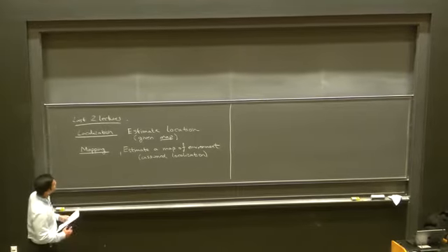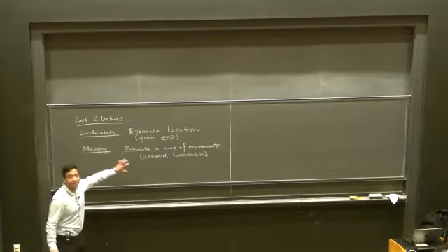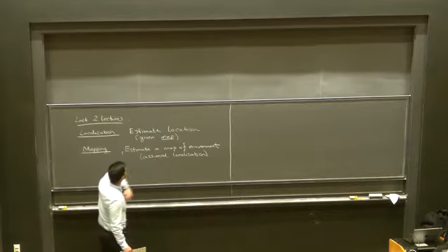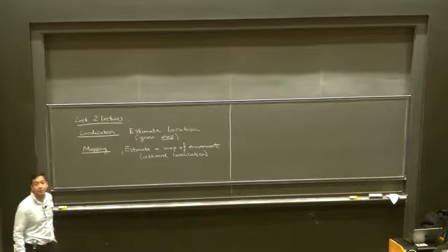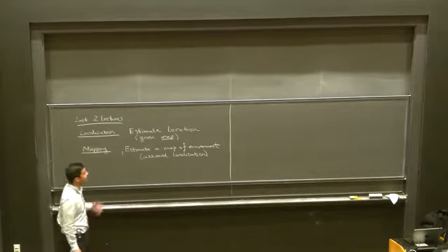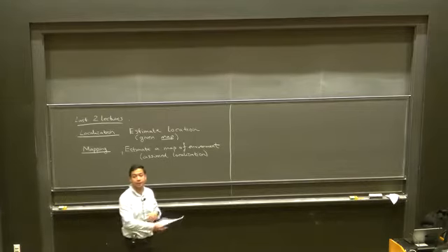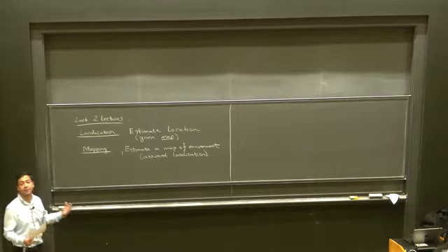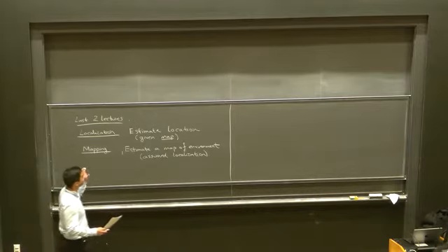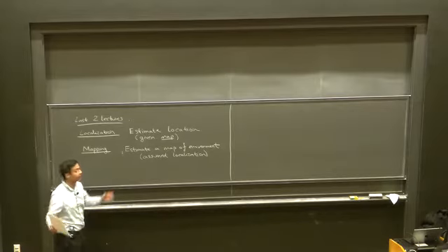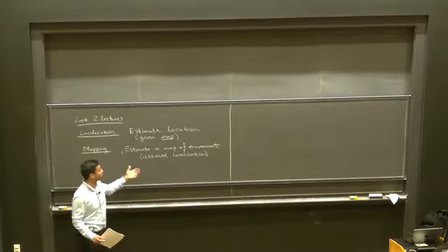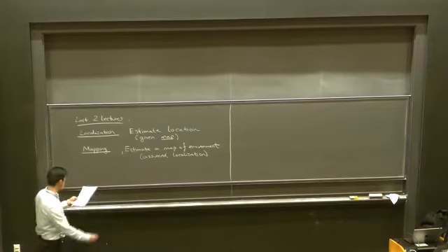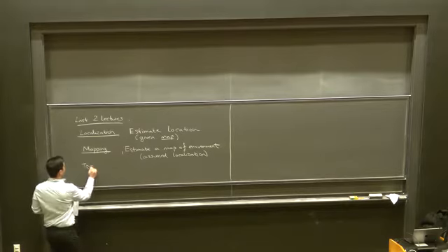So if you think about this, neither is completely satisfactory, right? For localization, we were assuming that we had a map of the environment. For mapping, we're assuming that the robot can somehow localize itself. In practice, what you'd like to do is just deploy a robot in some new environment and do both of these things simultaneously. So the robot should be able to figure out its location, maybe in some reference frame, and also as it's moving around, it should be able to build a map of its environment. So that's what we're going to do in today's lecture.